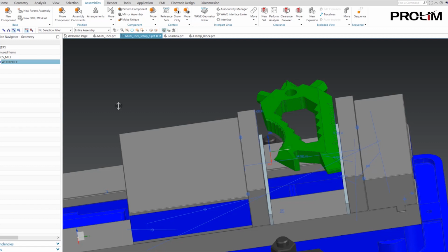But we still want to have the ability to make changes, any sort of manufacturing changes to the model for manufacturing purposes, such as a construction hole. Maybe you need to alter a corner radius slightly to adapt to your corner radius of your cutting tool, or maybe fit a tolerance a little better and move a face a couple thousandths here and there. This way the manufacturing changes made will not flow upstream to the master model, but any changes made to the master model, either by the design team or customer, will flow downstream to your linked body here in the manufacturing environment. So this is why we wave link, and we'll use this step in every scenario today.